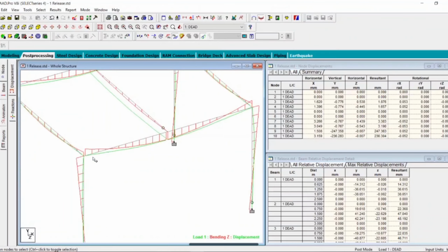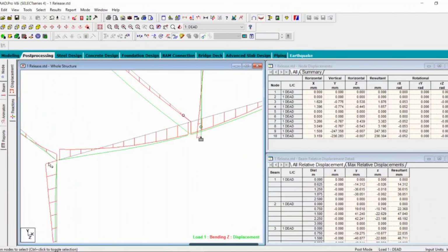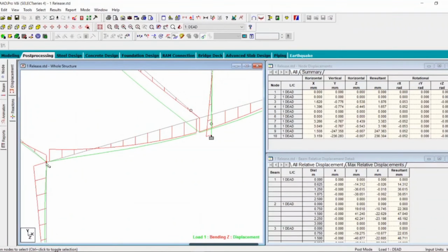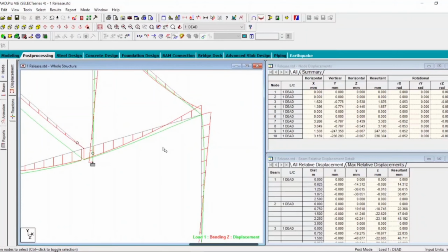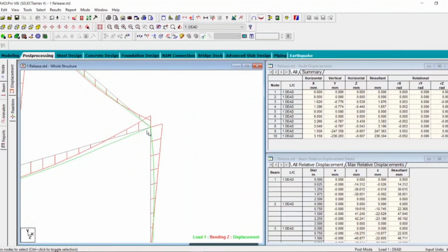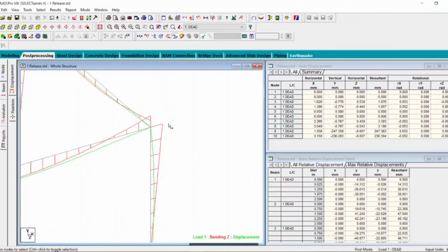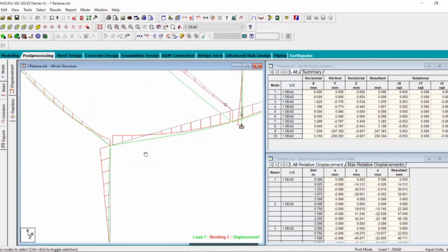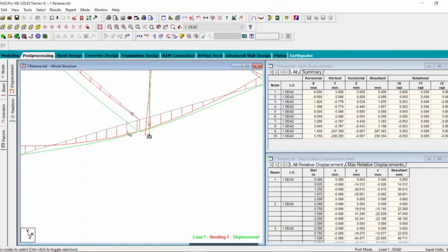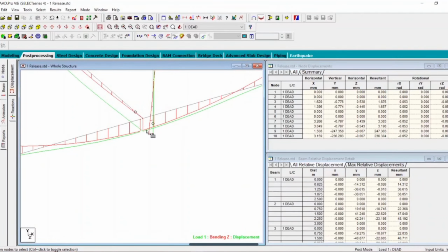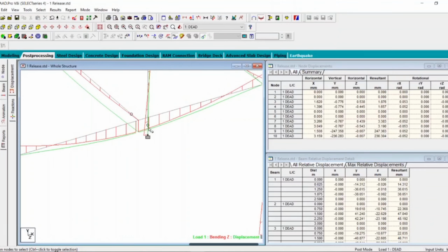Now if you zoom in, you see that your moment value is now displayed slightly away from the beam column junction. Similarly, if you see here, in this case, however, the moment diagram has been displayed from the beam column junction. Now you can see that this beam is a more realistic approach. Okay, I did offset here as well, but there is only the secondary beam, and you need not offset in the secondary beam position. You have to offset the secondary beam here, not the main beam.